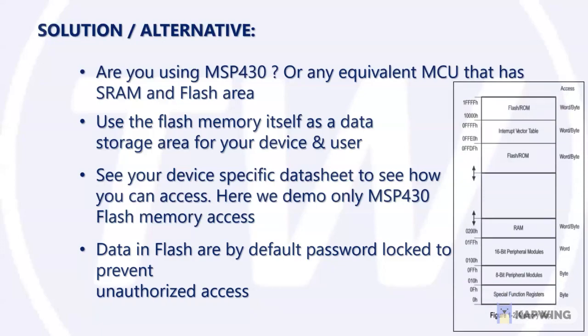If we are just taking into consideration a simple MSP430, you can see over here, let me just turn on the, here you can see that the RAM is there, which you can use to store your data. But again, remember that the RAM might be flushed out. So if you need to store your data in a non-volatile manner, I would recommend you to use the flash or ROM area. Now, if you're using the flash, then obviously there are certain areas where your own code is stored. So it's better not to clash with that area.